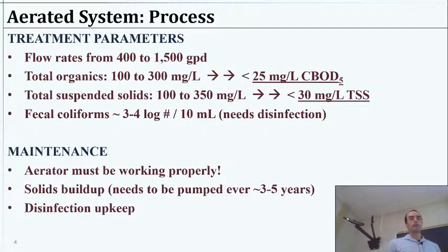If you had a stream that was entirely made up of this type of water, well, at most, your saturation of oxygen in water is going to be around 8 milligrams per liter. So with no air exchange, that would go anoxic very quickly a couple times over, right? With some air exchange or some time to let that happen, maybe it's okay.